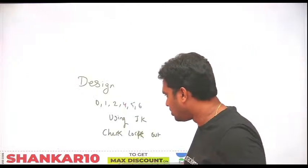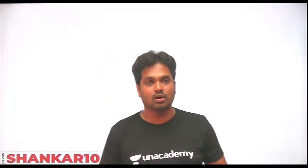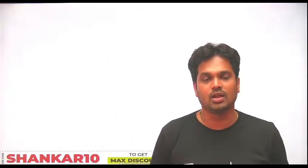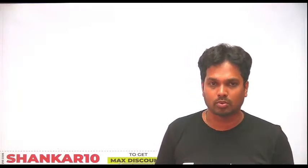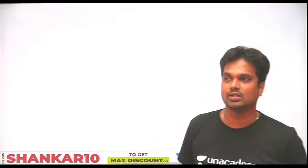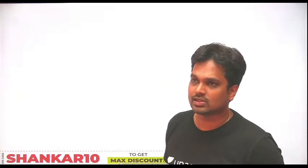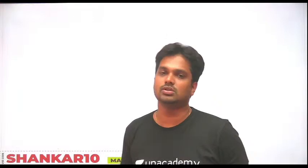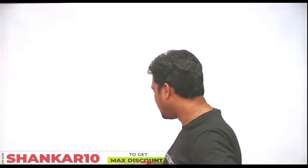So what is the meaning of lockout in the synchronous design? If by chance the counter enters into any one of the unused states, it never comes back to the used state. That condition is called lockout problem. When lockout occurs, we need to restart the system or redesign by taking the next state of all unused states into any one of the used states. Right, guys? That is how you design any synchronous system.